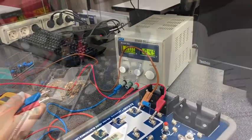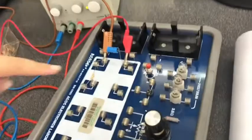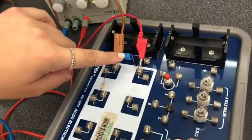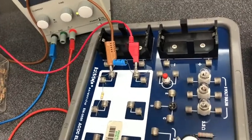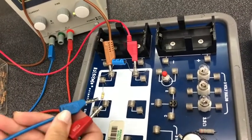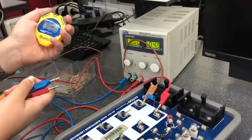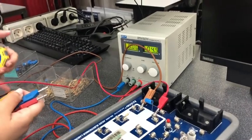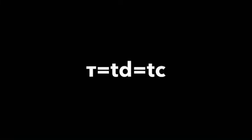Now, if you want to discharge your capacitor, first you have to fully charge it. You want it to reach 5 volts initially, and then you start to discharge the capacitor. The timer starts from 0 while the voltage is set at 5 volts, and then the time runs until it reaches 63% of change. It would drop by 3.15 volts, so it will reach 1.85 volts.